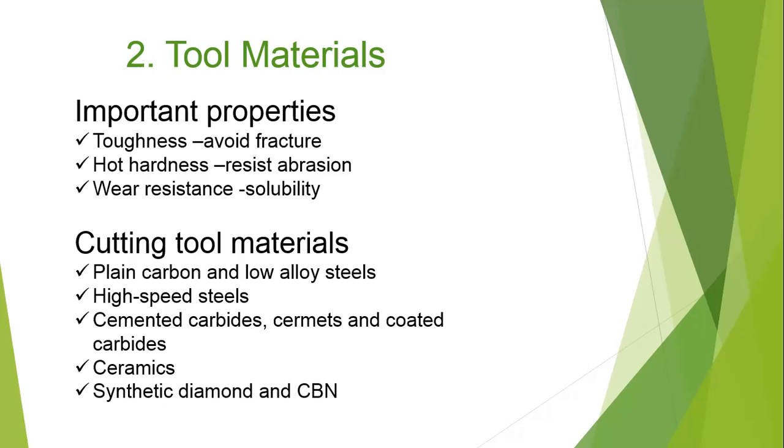Hardness is the single most important property needed to resist abrasive wear. All cutting tool materials must be hard. However, wear resistance in cutting depends on more than just tool hardness because of the other tool wear mechanisms.